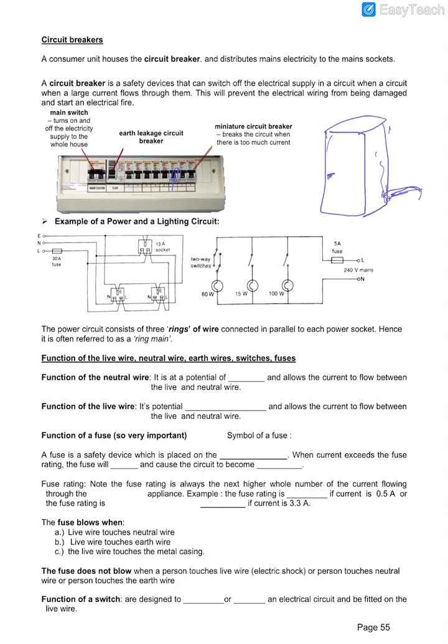When this switch goes down, I ever tried before. Last time my house had some problem. Don't know what's the problem. I pushed it down, it came down. I pushed it back up, again it tripped. Keep on tripping. So the whole night no electricity. Then I called the electrician. The electrician came and discovered that one of the multi-socket adapters was spoiled. It was drawing a lot of current, so that's why it kept on tripping. So I removed it, then everything was okay already. So these are all very important safety devices.